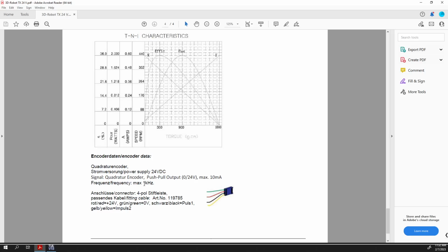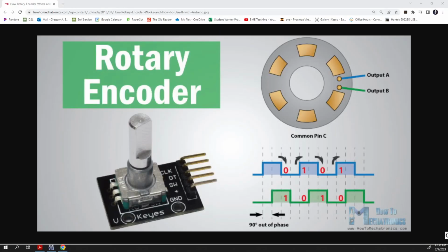But anyway, there's also two different types of counters. So traditional rotary encoders are actually pretty simple in the long run. Here you can see we've got a simple disk that has holes through it basically. You can also see we've got two little sensors here. When input A is lined up with this hole, it's true. When input B is lined up with that hole, it's true. So you can see as we would rotate this slightly, get my pen out, this hole would start to move down.